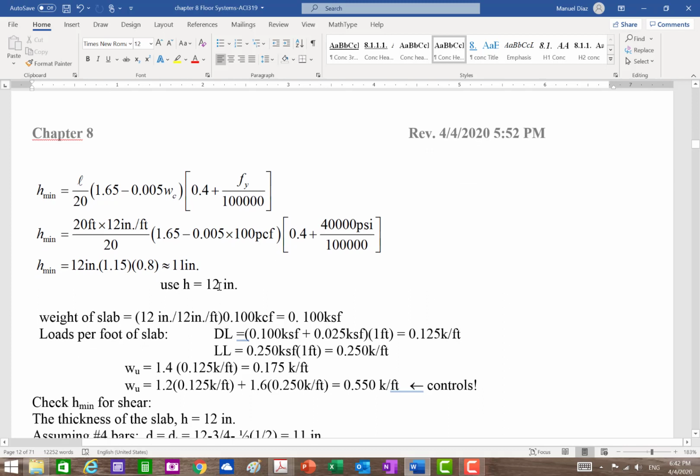Now, in slabs, probably going 11 to 12 may not be a good idea, especially in economy, because you may have a big slab, lots of concrete, right? And so even though it's 1 inch, 1 inch by, another 3,000 square feet or 40,000 square feet of slab, right? It's all the concrete. And so you may want to consider maybe 11.5 or 11.